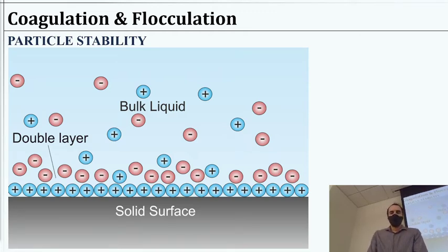We'll see. All right. Today I want to pick up where we left off with coagulation, and then essentially cover flocculation. Flocculation itself is not a particularly difficult or challenging process. There are several equations that will go into it, so to give us some way of knowing how many particles do we have that are going to stick together compared to what we started with. That'll give us some information about how big the particles are going to be, but ultimately it's just going to be a simple mass balance for flocculation chambers.